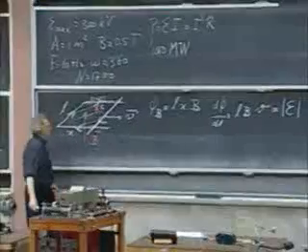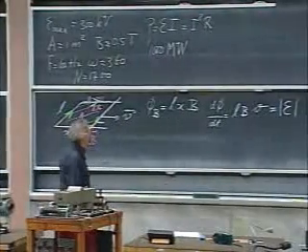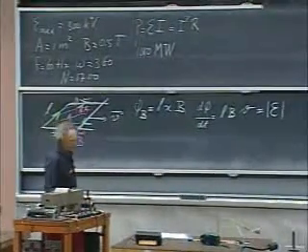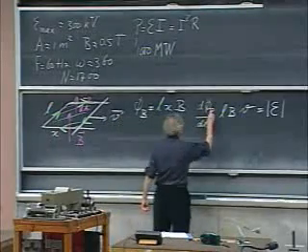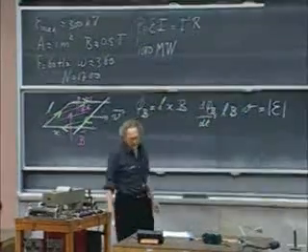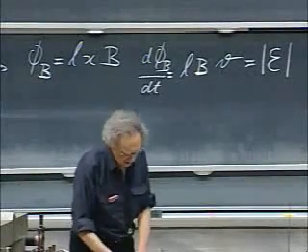And if I go in the other direction with the velocity, then of course the current will reverse. Φ = LxB, I can live with that. dΦ/dt, I can put a B here, if you like that, to remind you that we're dealing with magnetic fluxes: LBv, I'm happy.